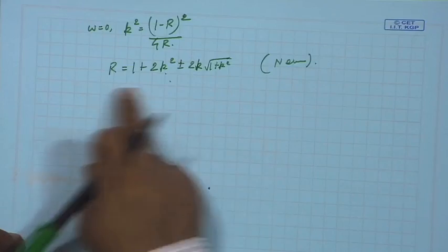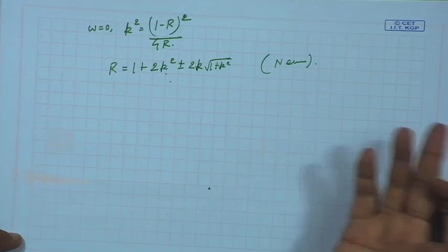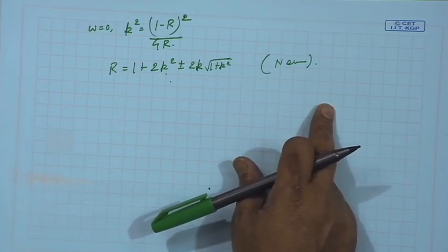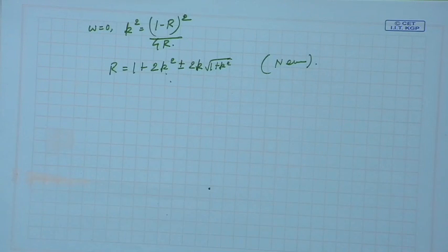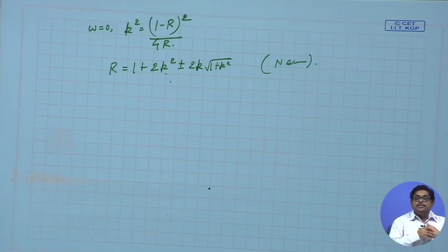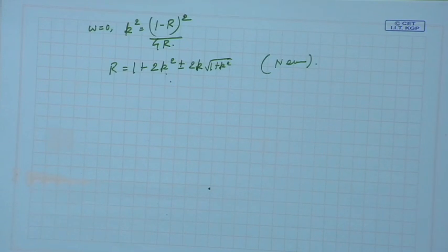Suppose you are having n even, you see this problem comes in n even, but if n is odd, then this is not there, r is equal to 1, that we have already seen. So, you can also do that, because for odd n, r is always 1 for Chebyshev. So, you try to make n odd there. So, you can design for various ripple values; these tabulations are available.